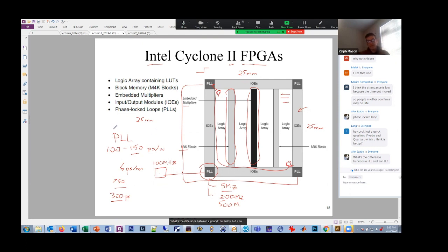An FLL stands for frequency lock loop. And there's also a thing called delay lock loop. There's three kinds of categories. The phase lock loop compares the phases. So here, where we want to get the right clock phases, it's super important to have a phase lock loop, okay? To line up the phases so the clock edges are lined up.